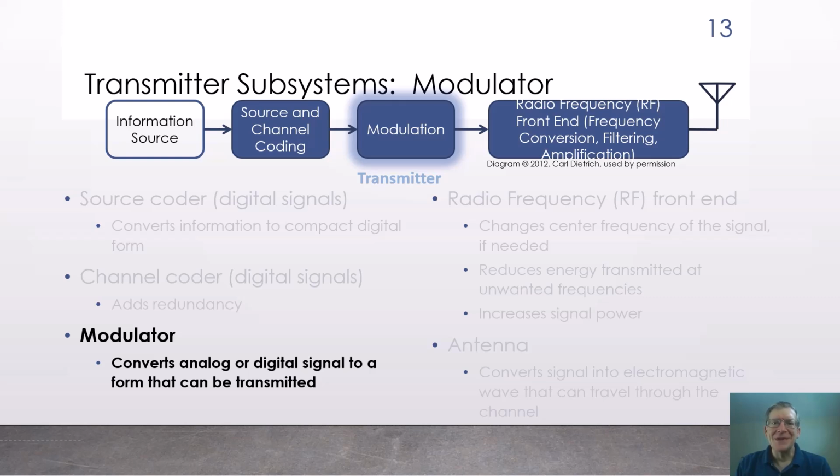In the case of a digital signal, the modulator output is in the form of symbols, which are time-limited segments of a modulated signal that represent a finite number of bits. A number of symbols can be transmitted consecutively, and such a sequence is called a frame and typically includes header information that tells the receiver how to process the signal.